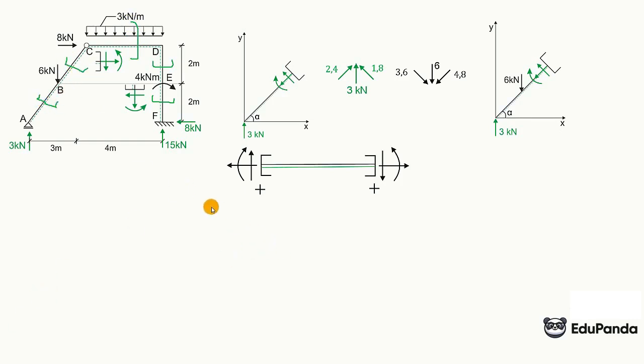So first, we are interested in drawing the normal force graph, meaning compressive and tensile forces. By doing this on the slanted rod, looking at this section, meaning from this point hiding everything on the right side, and we see only the supports A, we are interested in the normal force to the rod. So here will be only the normal component of this triple, meaning 2.4. It compresses, meaning the direction is opposite to what is shown here, so it's negative. Then, as we move to this second section, besides having the 2.4 that compressed, an additional normal component from 6 appears, which is 4.8, and it stretches.